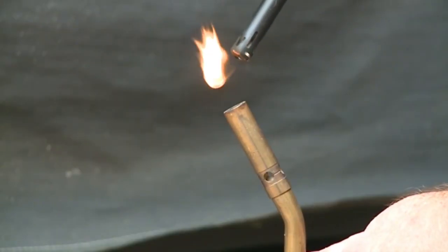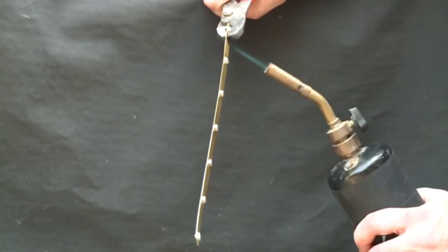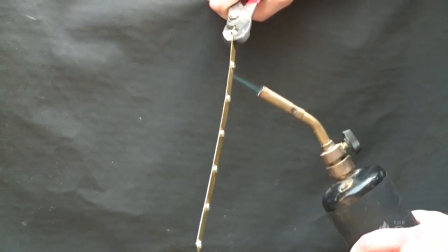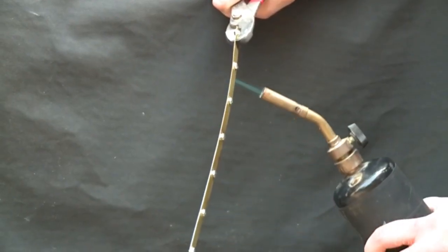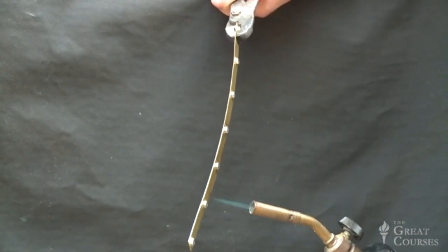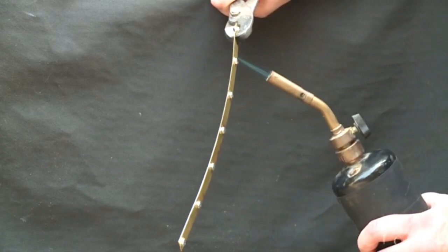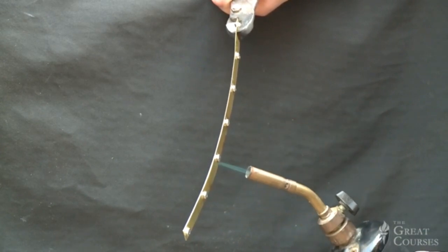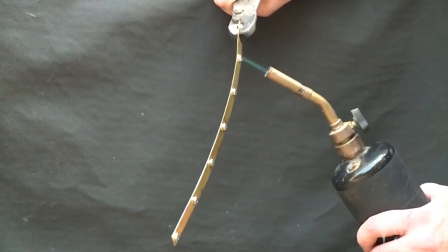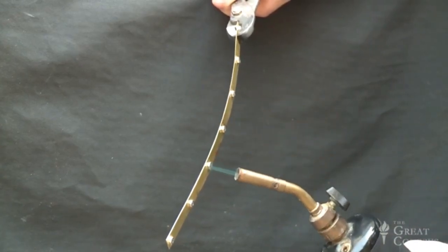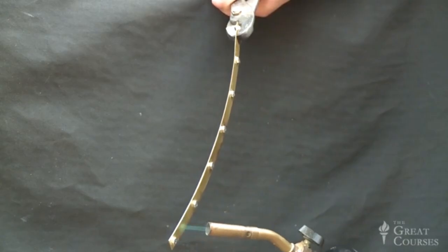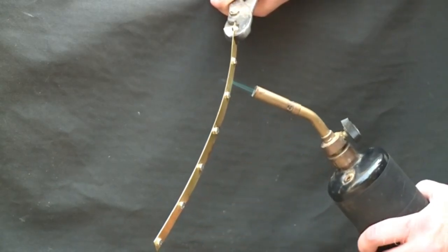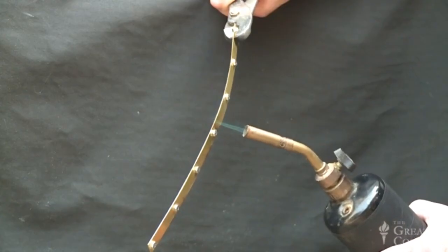Now, I can't actually fire up my torch here in the studio, so let's watch this video that illustrates how the bimetallic strip actually works. Here I'm adding heat to the bar, and as it heats up, if you look very closely, you can see that it begins to bend. The effect clearly is quite subtle, but it's very important to recognize that the amount of bending is large enough to be measurable, in sharp contrast with the longitudinal expansion of either metal, which we've already calculated to be less than 1/100th of an inch.